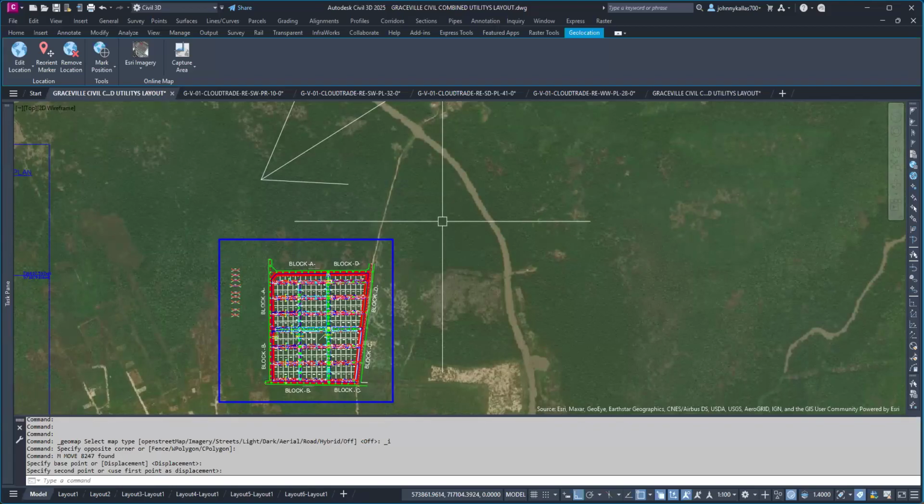It is very challenging to construct this road if you are filling 3 meters high at some point and the plots will not be filled. So there should be a baseline filling which all stakeholders agree to. Then when you want to start your construction, you can fill to your required level. But the bottom line is that we certainly need sand dumps around the layout.